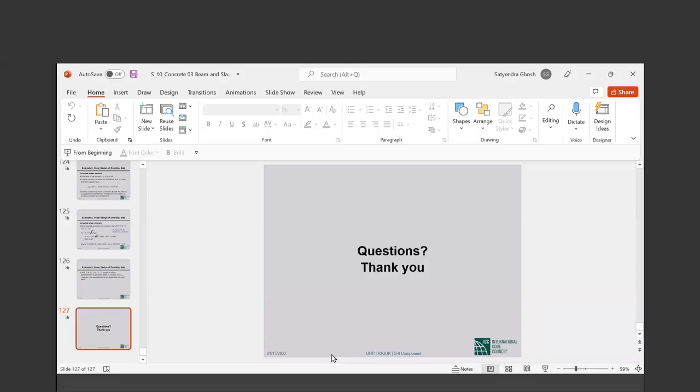Read that last sentence again. The diagonal shear rebar, horizontal and vertical shear rebar, and the flexure rebar all together create such congestion that concrete pouring becomes difficult. Yes, I agree. So you have to be very mindful at the design stage. This is true in all situations, particularly high seismic design.